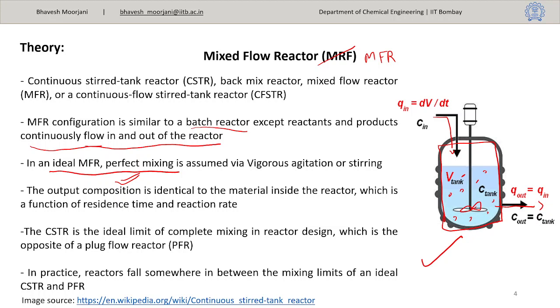And gradually the concentration gradient will change. So that will be a concentration profile across the reactor. While in CSTR, inside the reactor at every point concentration and temperature are uniform. Okay, so that's why if we talk about complete mixing, CSTR comes at one end of the spectrum, while PFR comes at the other end. In PFR you can observe gradual change of concentration with the reactor length, while CSTR is the opposite end where complete mixing is happening.